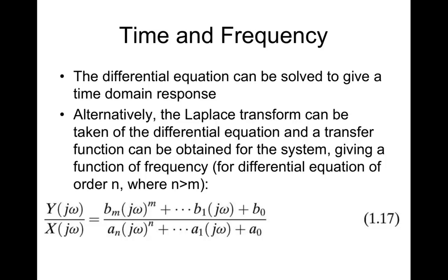If we're interested only in the frequency response and we're not interested in the temporal response, we can take the Laplace variable s and we can let it be j omega, in which case that differential equation transforms to something that looks like this form here, where we have powers of j omega, meaning that if we have a sinusoidal input of a specific frequency, so if omega is known, we're basically going to have an output that has both a magnitude and a phase in general.